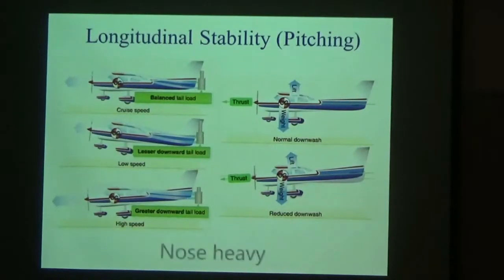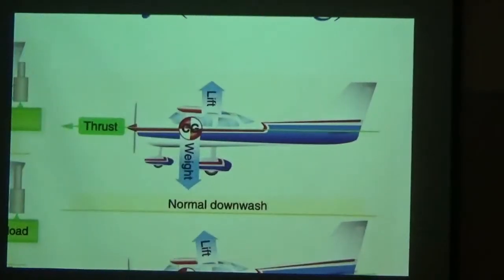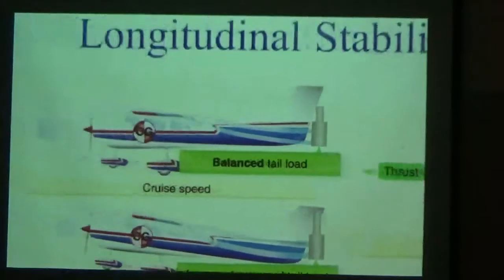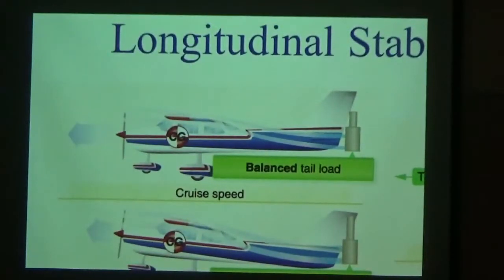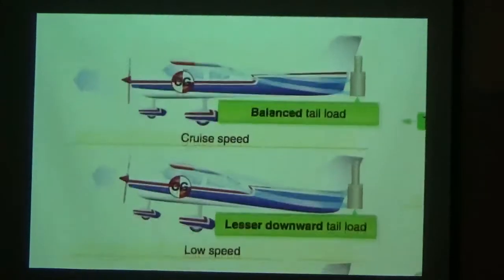Most aircraft are designed to be nose heavy, with a center of gravity that is in front of the center of lift. Even when the horizontal stabilizer is level during flight, downwash from the wings pushes the horizontal stabilizer down. Generally, the manufacturer of the aircraft will give the horizontal stabilizer an angle that will provide the most stability during flight at a given speed and power setting, as shown above.